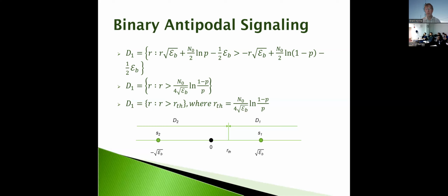The signal's really strong, or they may be way far away from the base station, at the very edge, and so the signal is very weak. It's dissipated in the propagation, and so you change the modulation depth. You change whether it's BPSK or QAM or 16 QAM or 1024 QAM type of thing, and that changes your effective data rate.